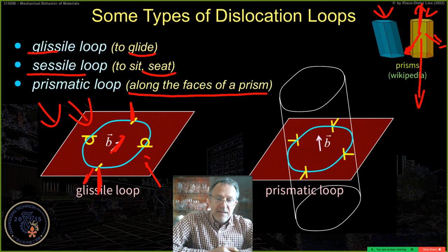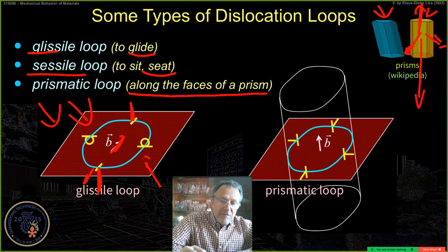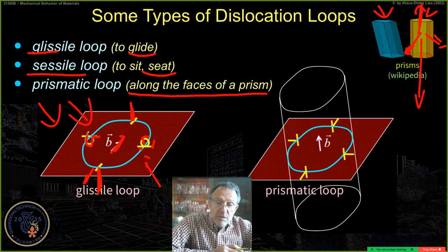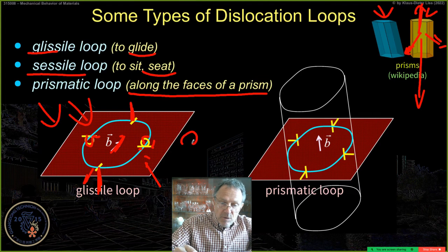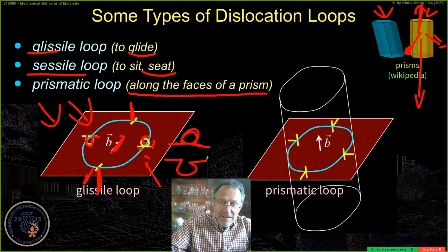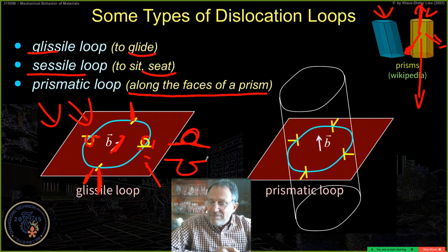It depends how you see it. And then on one hand we have a left-handed, and on the other side we have a right-handed screw dislocation, which may be shown by those symbols. So a screw is something which goes around the cylinder, and then we put this bar to the bottom or to the top. So it's something like an omega and a bottom omega on the other side.